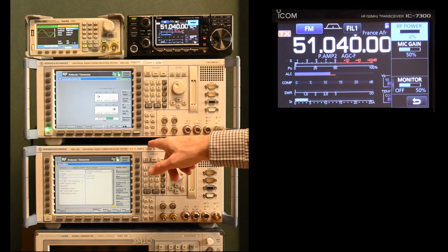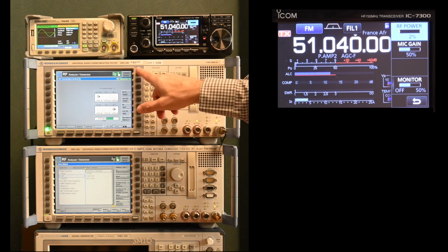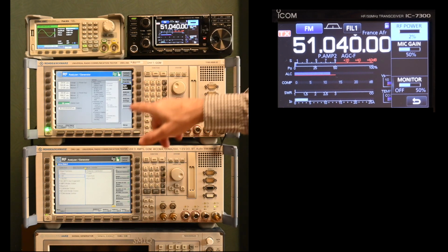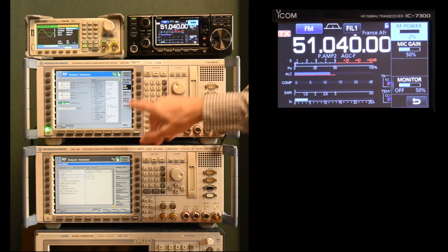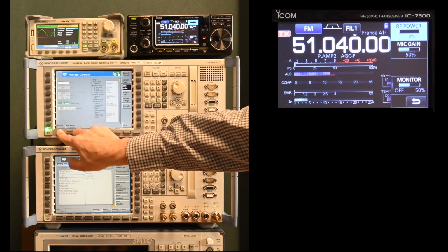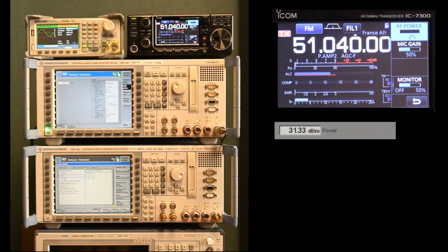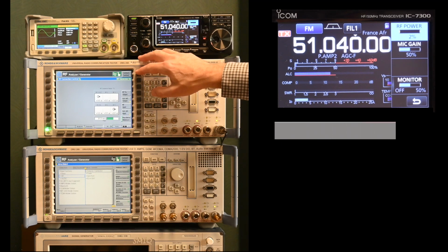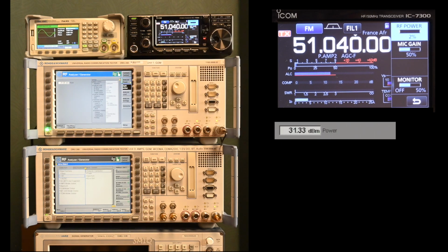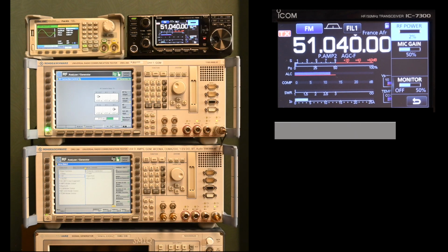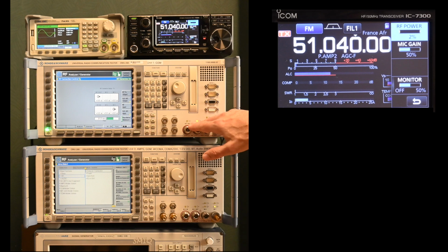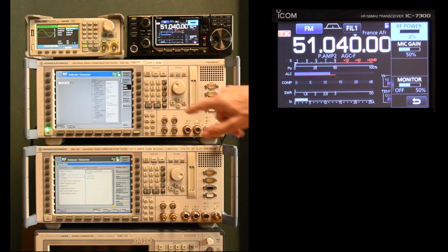There's also a dedicated application for looking at wideband power levels. So we would go to the power meter menu here. And right now we select wideband, and we get to see exactly the same type of measurement as we get over here. Actually, we see it in a slightly higher resolution. We see 1 digit more. I believe this one, like the one in the Connect Control menu, is on one of the power diodes that are right away in the input unit of the device.